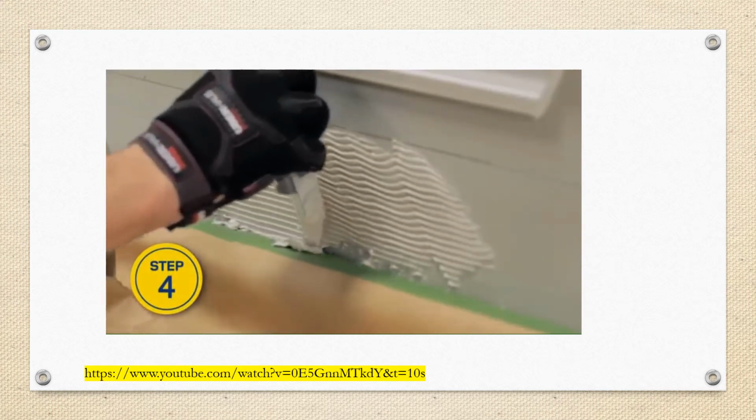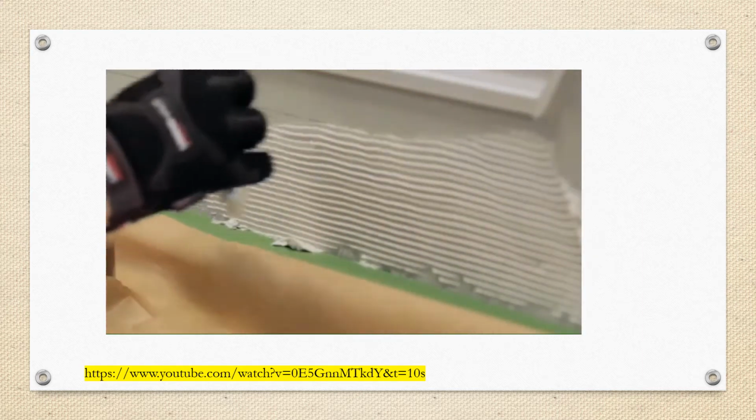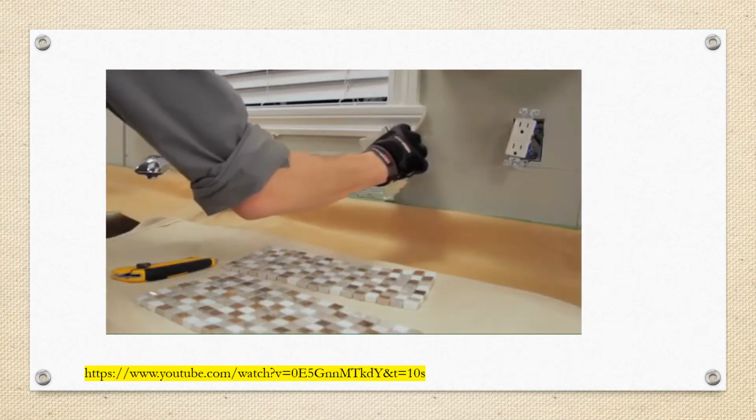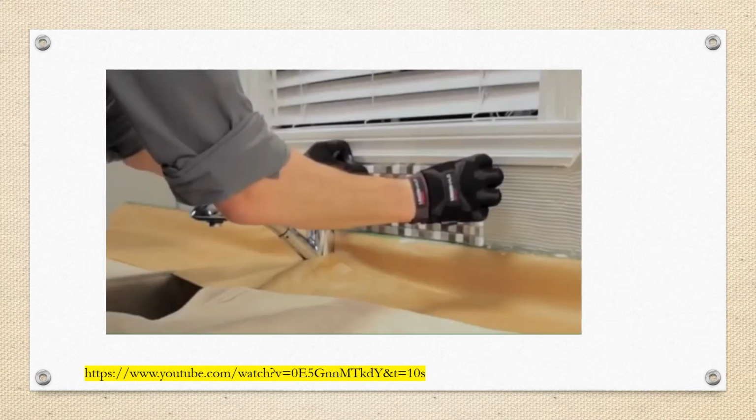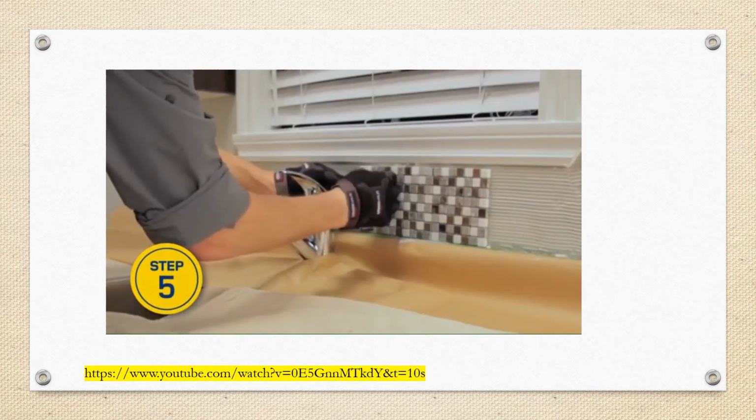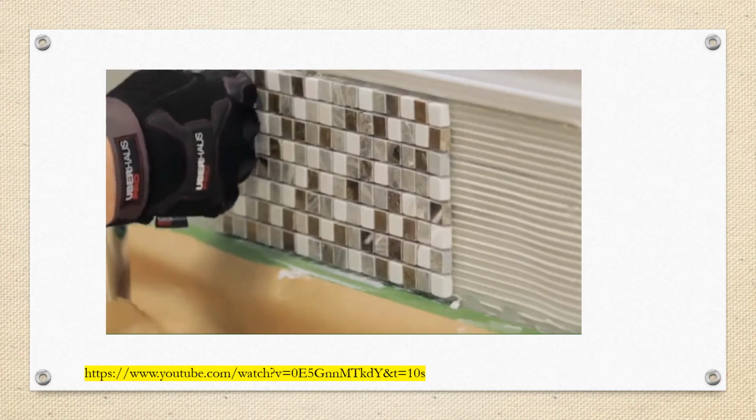With the notched side of the trowel, make grooves in the adhesive. The grooves should all be made in the same direction. Dampen the adhesive if it starts to harden. Lay the first mosaic tile sheet. Cut sheet to fit if necessary.